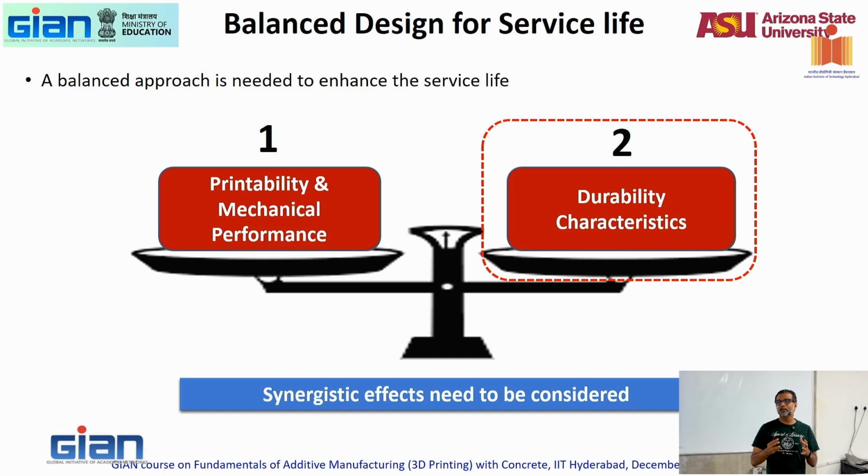Now, a lot of times in conventional concrete structures, reinforced concrete structures, your durability is strictly a function of corrosion of steel. If you're a reinforced concrete structure, your durability mostly is defined by corrosion. There is sulfate attack, there is ASR, there is acid attack, there are lots of other things. But in a structure that is in service, the one that really bothers you the most with respect to durability is not the problem of concrete itself, but the problem of putting steel in concrete, right?